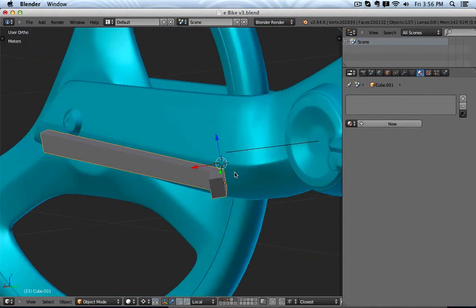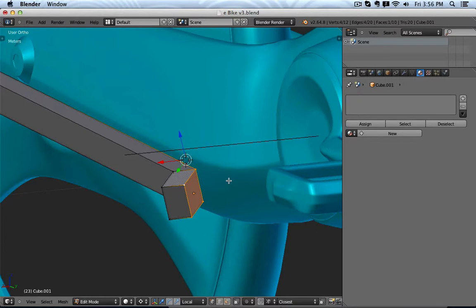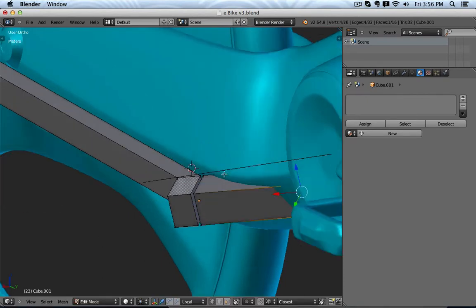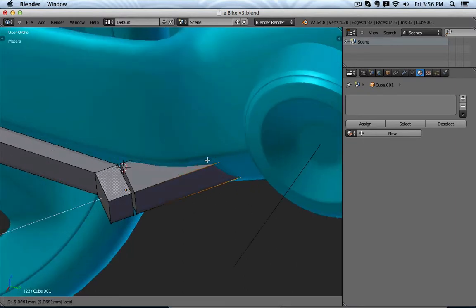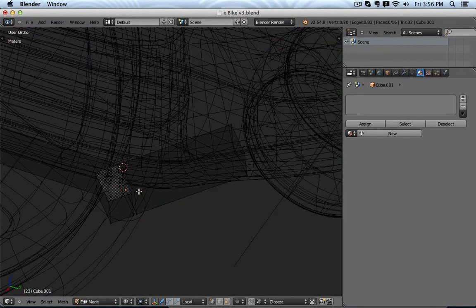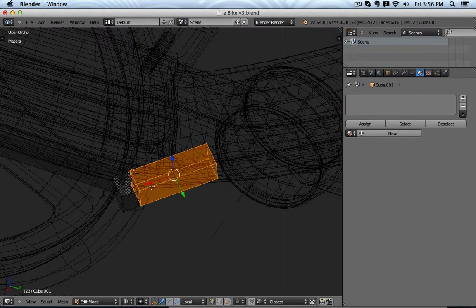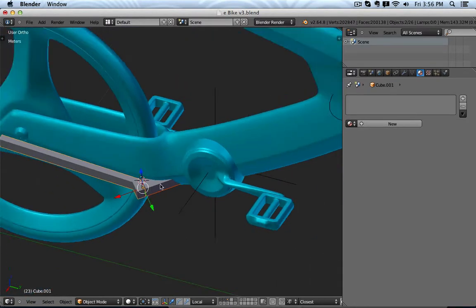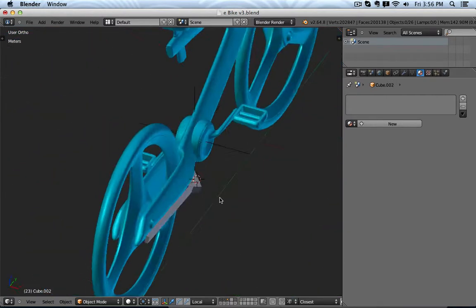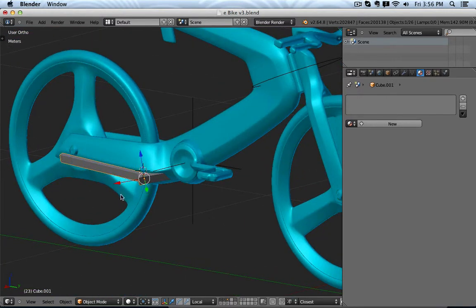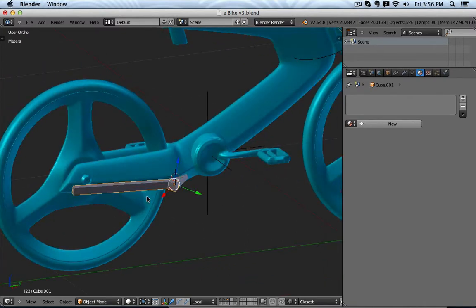Okay, and I can maybe select those faces, duplicate them, move them in local space a little bit, extrude them out a notch more, push them in, and maybe with L select all those vertices, press P to separate it, so I have two separate objects. And then I can simply click this object, R X X, maybe type in 90 plus 45 is 135 degrees.